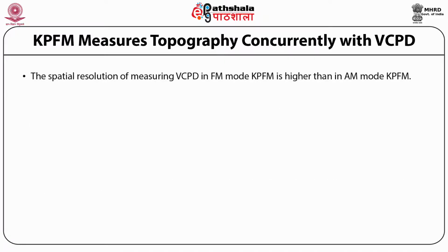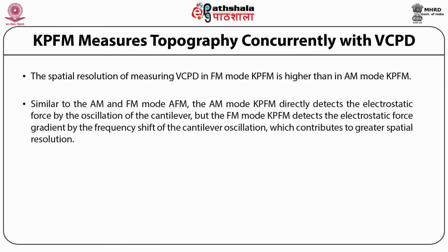The spatial resolution of measuring potential of CPD in FM mode KPFM is higher than in AM mode KPFM. Similar to the AM and FM mode AFM, the AM mode in KPFM directly detects the electrostatic force by the oscillation of the cantilever, but the FM